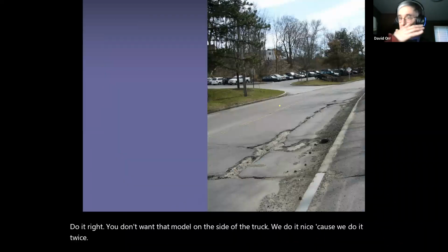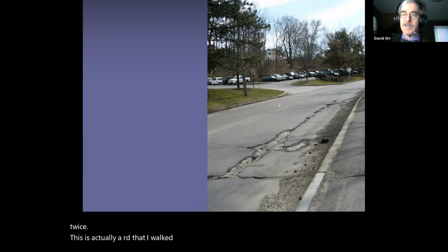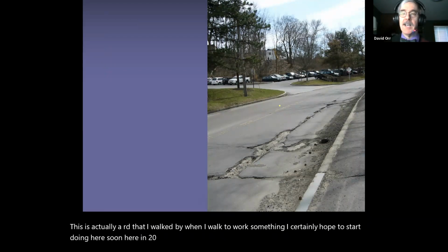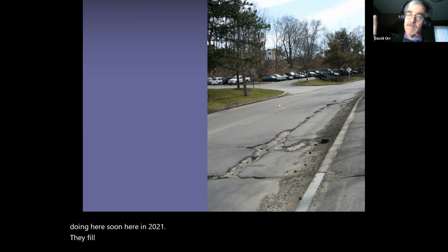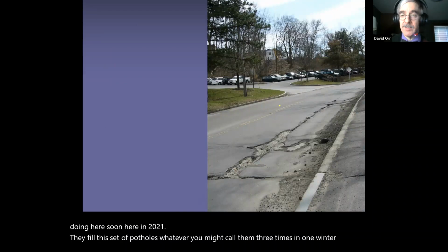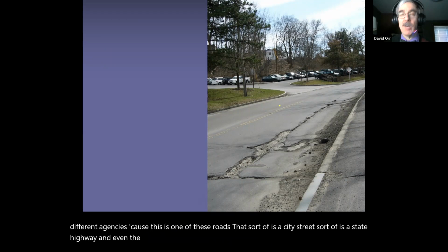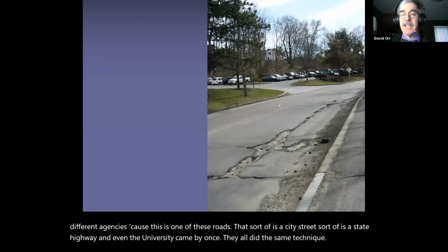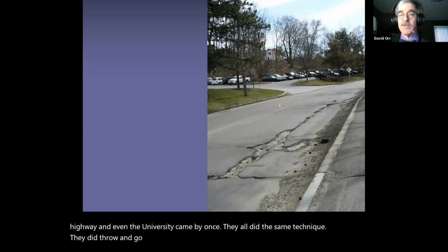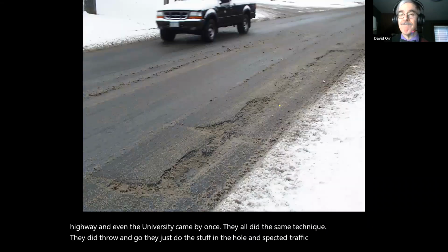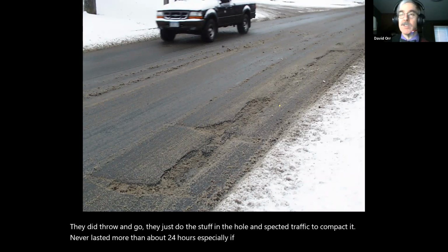This is actually a road that I walk by when I walk to work. So something I certainly hope to start doing here soon, here in 2021. They filled this set of potholes, whatever you might call them, 3 times in one winter. 3 different agencies, because this is one of these roads that sort of is a city street, sort of is a state highway, and even the university came by once. They all did the same technique. They did throw and go. They just threw the stuff on the hole and expected traffic to compact it. Never lasted more than about 24 hours, especially if there was any kind of snow and moisture coming along.